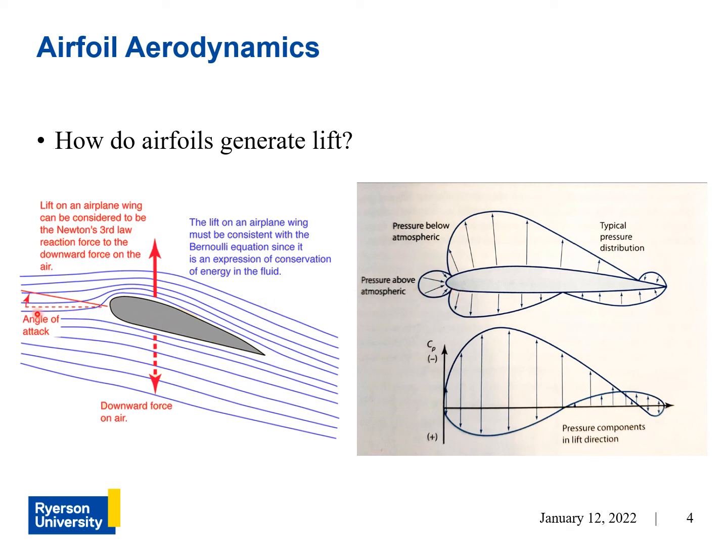So the main takeaway is that it's not the distance that causes the difference in pressure. It's the angle of attack or the camber, which has the same effect as changing the angle of attack, the camber of an airfoil.